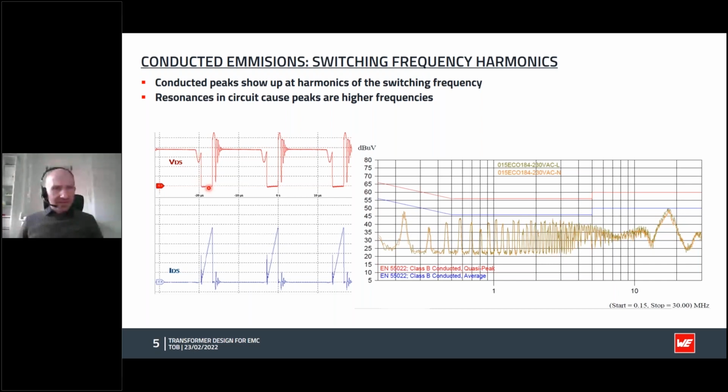Then we have a V-bus voltage on the top side of the transformer, and then we have 0 on the secondary side. So we have a large voltage across the primary winding, and that will cause current to rise in the transformer winding. So current rises from 0 in this case up to some peak, and then we turn off the switch.